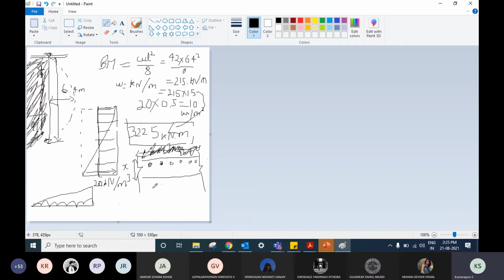Now let's take a 450 mm thick wall. I'm just assuming a 450 mm thick wall, which is X here. Let's take, instead of T20, a 25 mm diameter rebar. Okay, 25 mm. So T25 at say 150 mm spaced center to center.